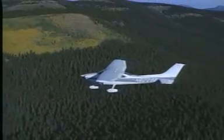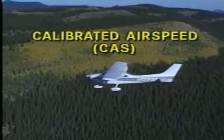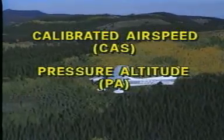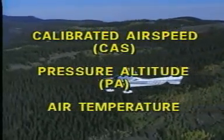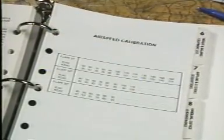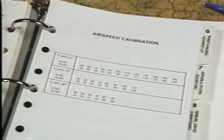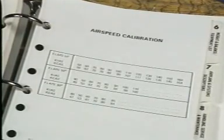To determine true airspeed, you must know three things: calibrated airspeed, pressure altitude, and air temperature. Calibrated airspeed, which is indicated airspeed corrected for installation and instrument errors, can be found by referring to the airspeed calibration table in the pilot's operating handbook.